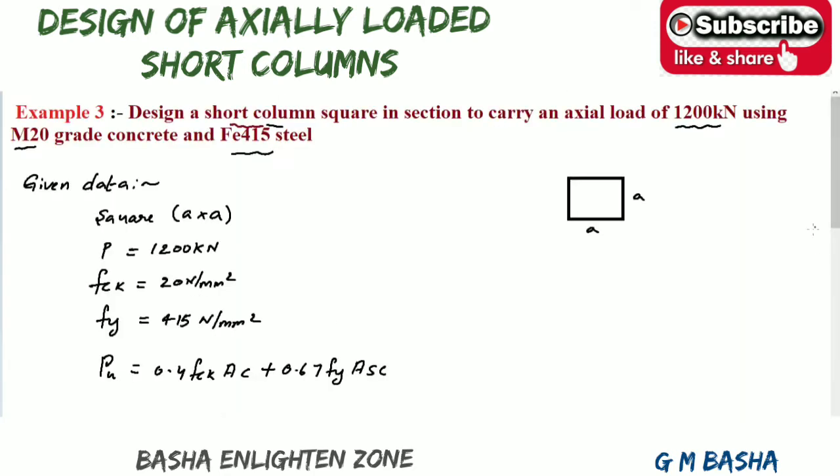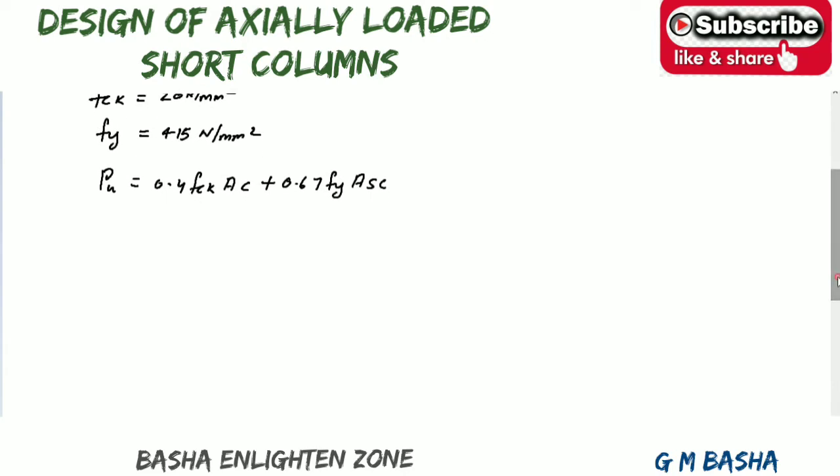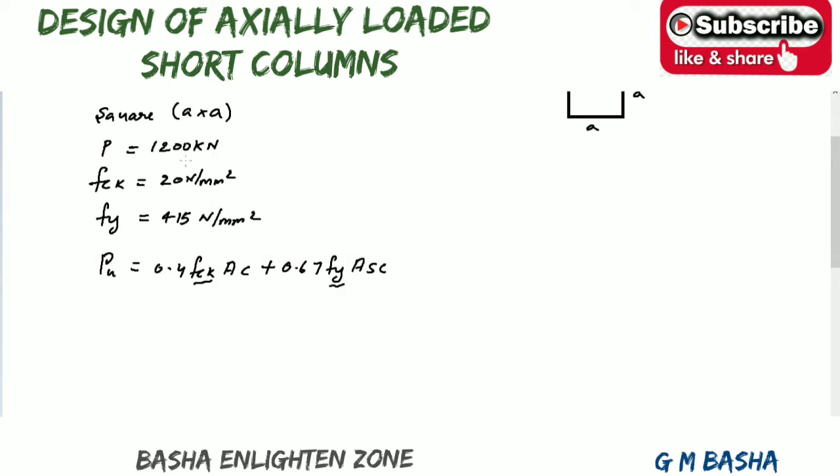See here, fck is 20 Newton per mm square, fy is 415, and the load is already given, that is 1200 kilonewton. Then find Pu, which is the factored load, that is 1.5 times the load which is given, 1200 kilonewton.